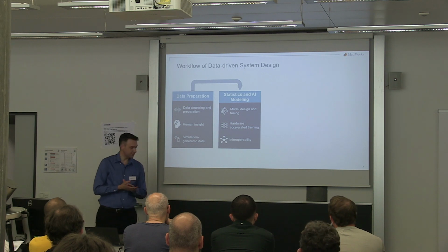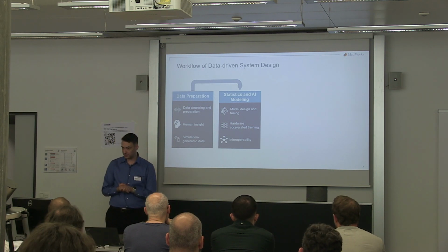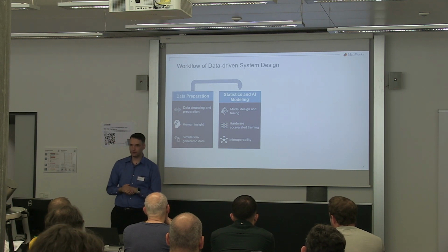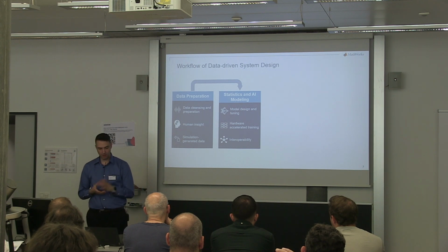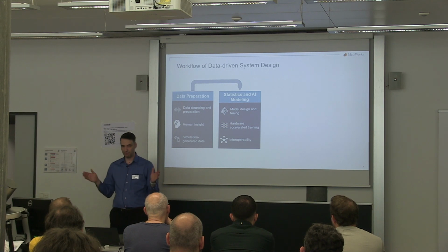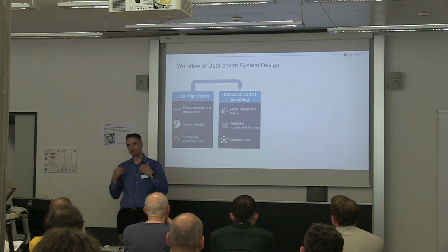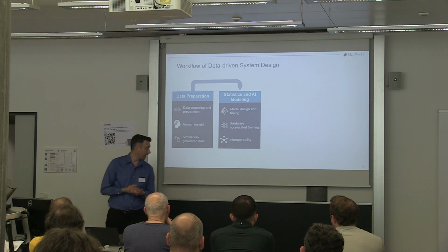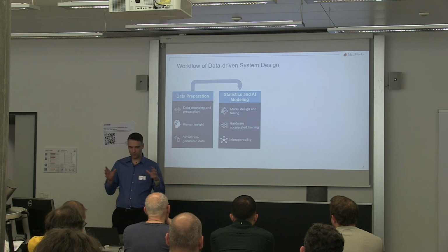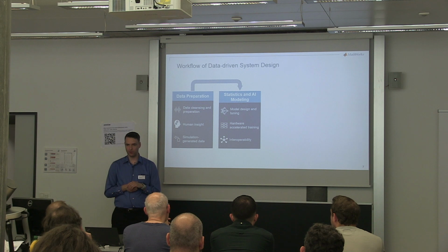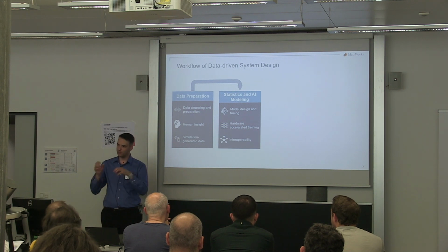Then we have the second phase. In our case, that was basically to work on the statistics, to be able to measure the distance between two consecutive peaks. But you can also add the artificial intelligence part to it, where, for example, you will have a look at the features out of the signals that would be relevant. You will extract these features and then train a deep learning model. This is something I have also done in this use case. You can use MATLAB to directly extract the characteristics, in this case using a wavelet transform, and then use them to train your deep learning model. Once the deep learning model has been trained, you can deploy it onto the hardware.